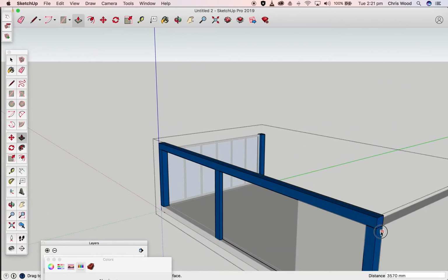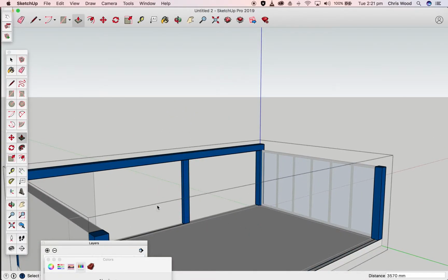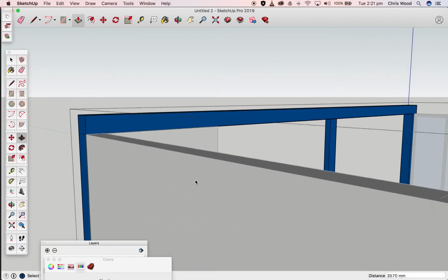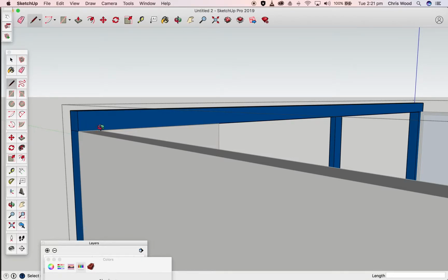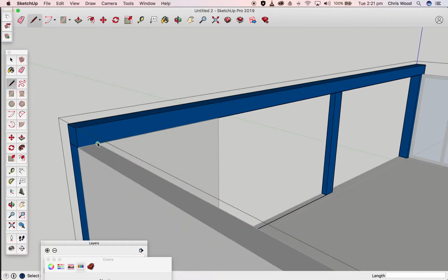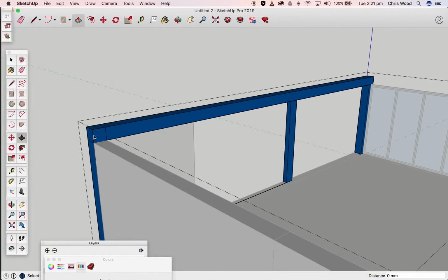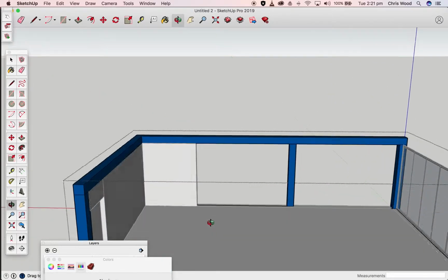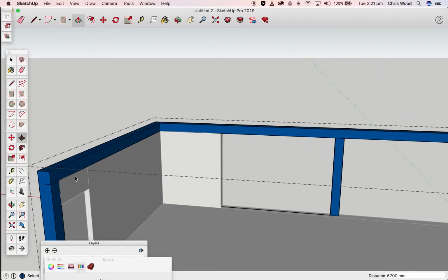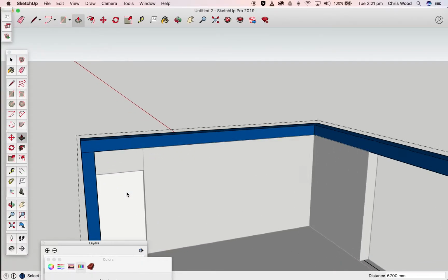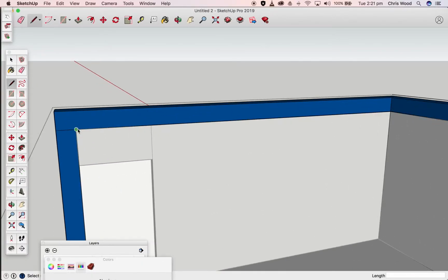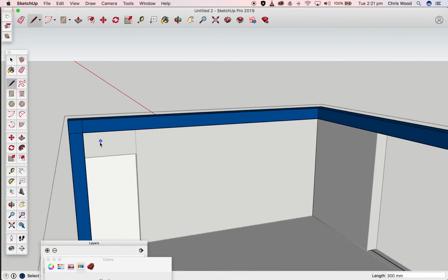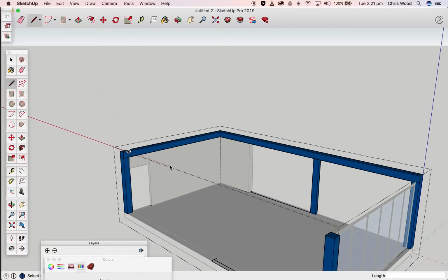Okay, so I can bring it right back to here, and then I can come over, I can block it off at this, I can just clip into this at 300, blue line tells me it's vertical, I can extrude this out, touch the line here, and then I'm going to do the same, come in 300, which I can tell from the structure. So I'm trying to keep this all quite modular and easy.